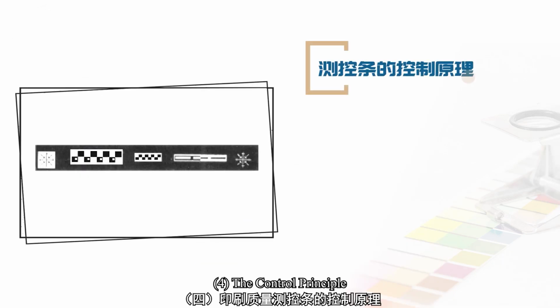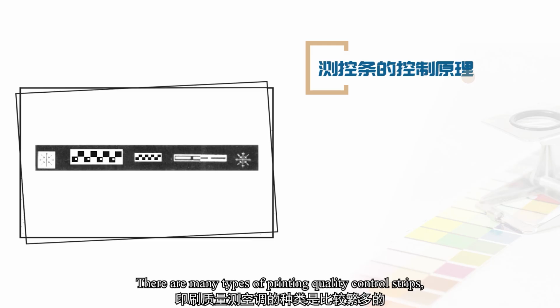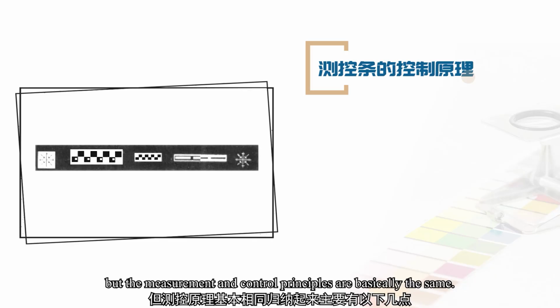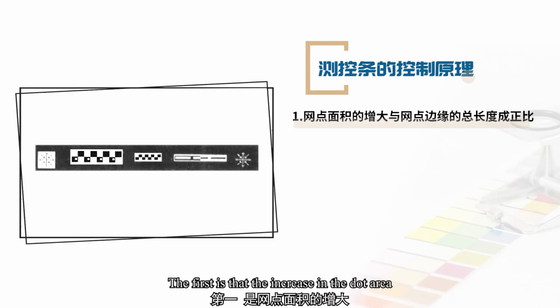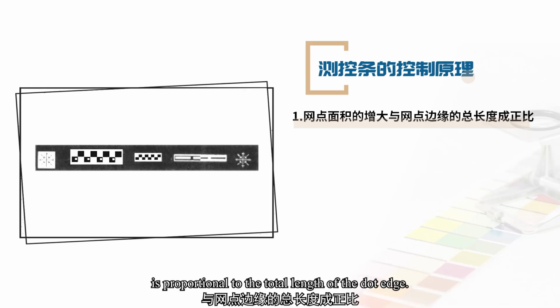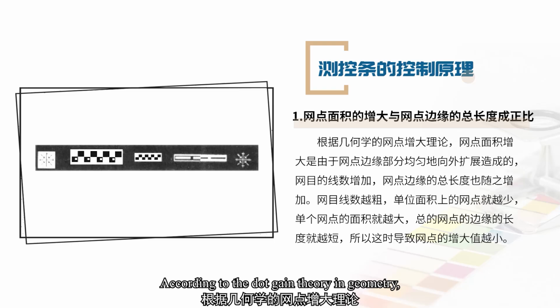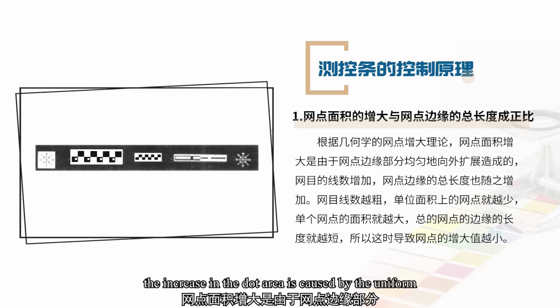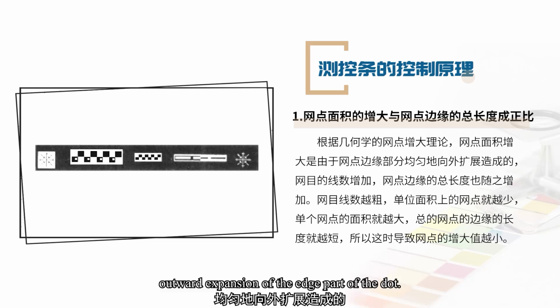Fourth, the control principle of the printing quality measurement and control strip. There are many types of printing quality control strips, but the measurement and control principles are basically the same. Summarized, they mainly include the following points. The first is that the increase in the dot area is proportional to the total length of the dot edge. According to the dot gain theory in geometry, the increase in the dot area is caused by the uniform outward expansion of the edge part of the dot.